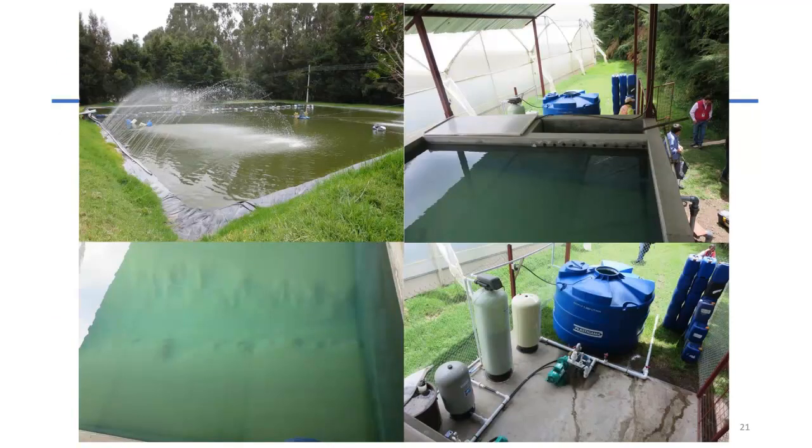So this is a photo. It's not specific to iron, but it's a system where they were trying to remove other ions. And you can see that it's very similar to what I was describing. They had first their catchment pond with multiple aeration systems. Some of them are off, but they're in the middle of the retainment tank there. Then they put the water in this concrete tank, and they added whatever was going to help with flocculation or oxidation. You can see that things started to settle at the bottom of the tank. And then they had an ion exchanger, and then some filtration to follow. So the system can be very simple. It looks a little more complicated in the cartoons, but even small farmers can do something along these lines.